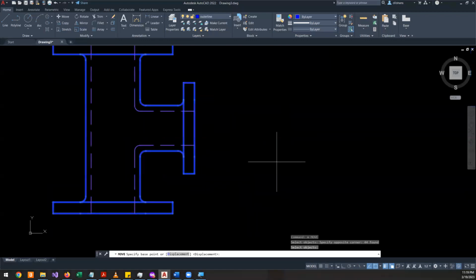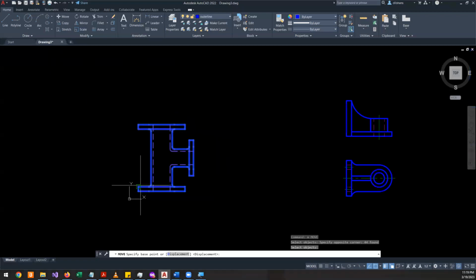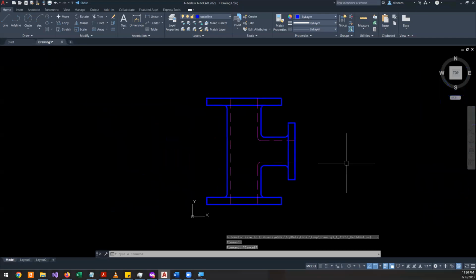Likewise, if I want to move these objects inside AutoCAD, I need to grab it. AutoCAD needs you to select that point, and without that, you will not be able to proceed. You can proceed, but you will get garbage results. So always you need to grab from a suitable point. This base point will depend on what you want to do. Say simply, if I want to coincide this point with this point, let me put a circle here.